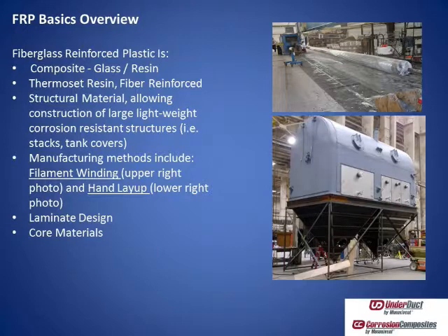You have a question. With laminate design, do you provide the engineering required for this project? We often primarily build to the ASTM standards, and there are formulas that we follow, but anything unusual, we then would do the laminate design. So the real custom things very often involve laminate design, calculations, and so on, but the typical duct system is built for ASTM and SMACNA standards.